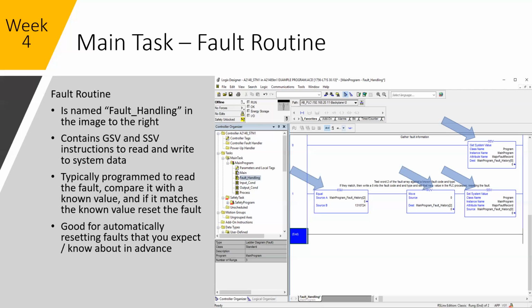So you would use a data array every time you saw a fault, push the array down, and then you could look at some historical data, possibly pull that with an HMI system. There's no real historical log in the controller. There is a spot where you can see some of them, but if you clear them, they're gone. They don't stay forever. And I'll try to show you an example of that. I might have an example of that.